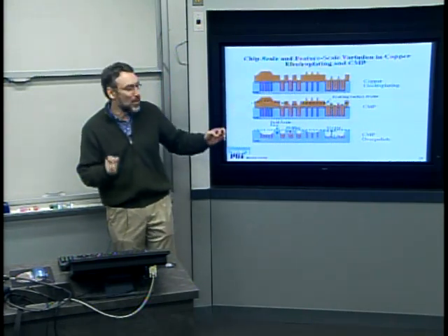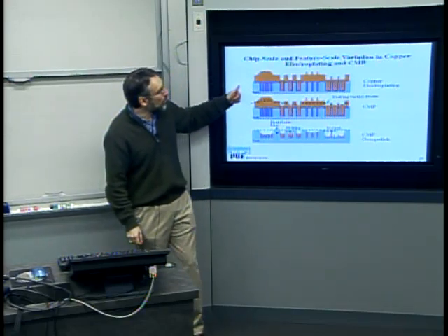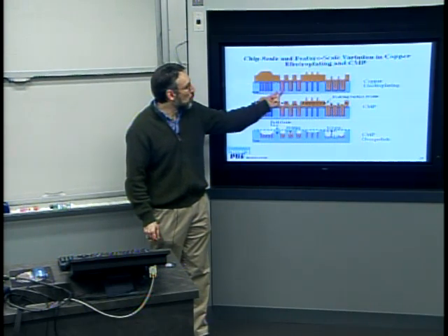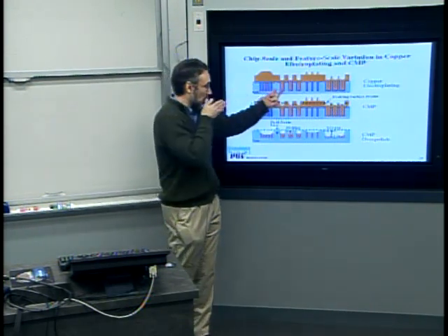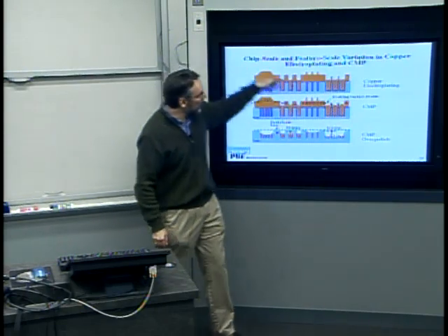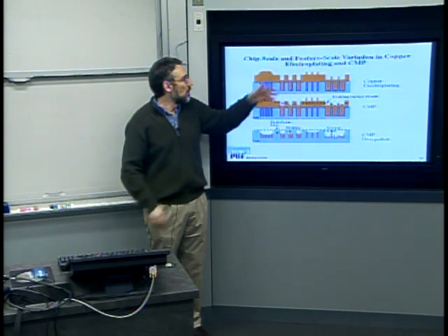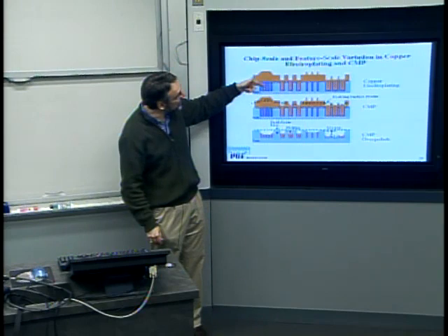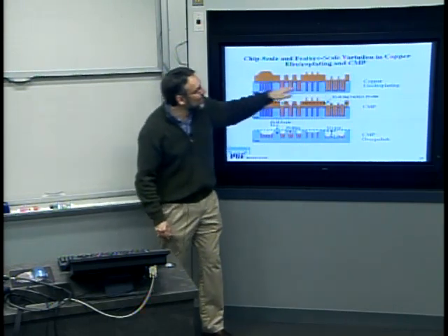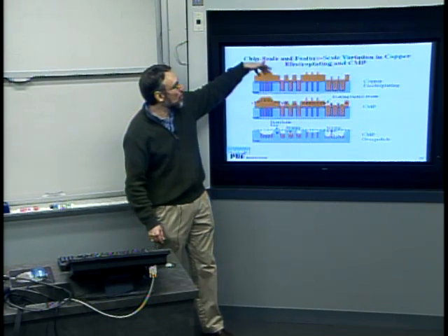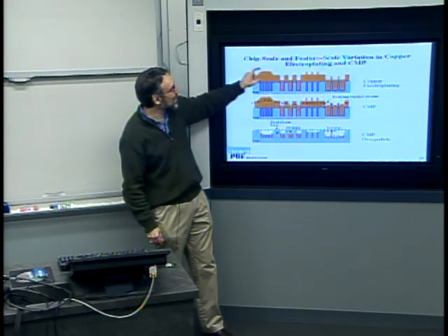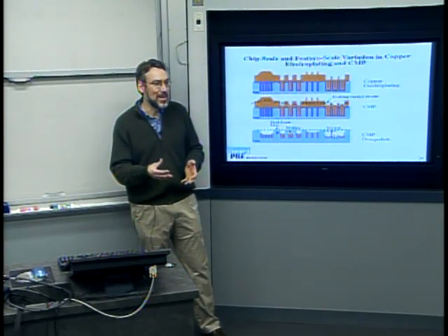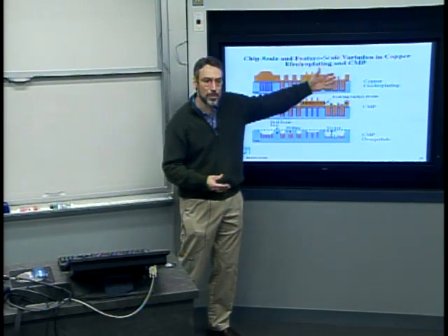So instead, what we have to do is go through the following sequence. We photolithographically etch in our insulating layer where we want ultimately the copper line to reside. Then we fill in copper everywhere. We happen to do that using an electroplating process. And that electroplating process results in nice filling of features of different sizes, but it also overfills. And even more problematic is it overfills to different amounts or different thicknesses depending on the feature size that we filled up. So you get this very complicated topography.